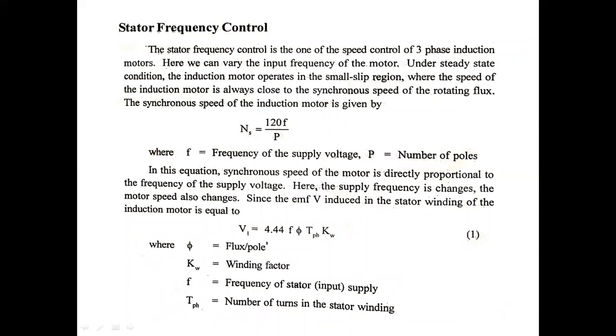Let me first explain how to control the induction motor. What are the relations holding for the induction motor with respect to frequency? Let me see the equation here. It is given as Ns equals 120 F by P. From this we can conclude that the supply frequency is directly proportional to the synchronous speed of the induction motor. Similarly, we can say that the rotor speed is also proportional to the frequency.